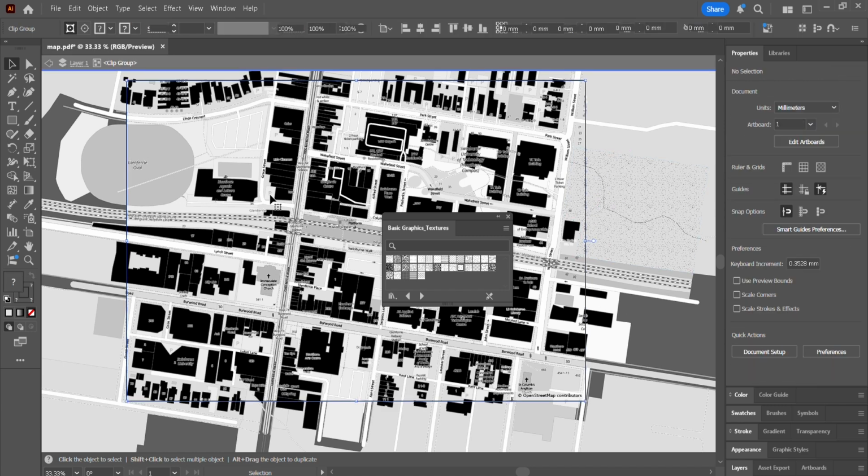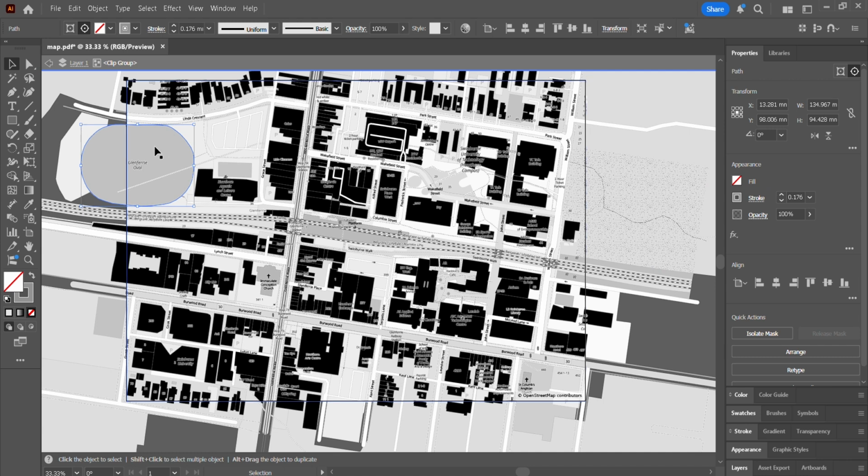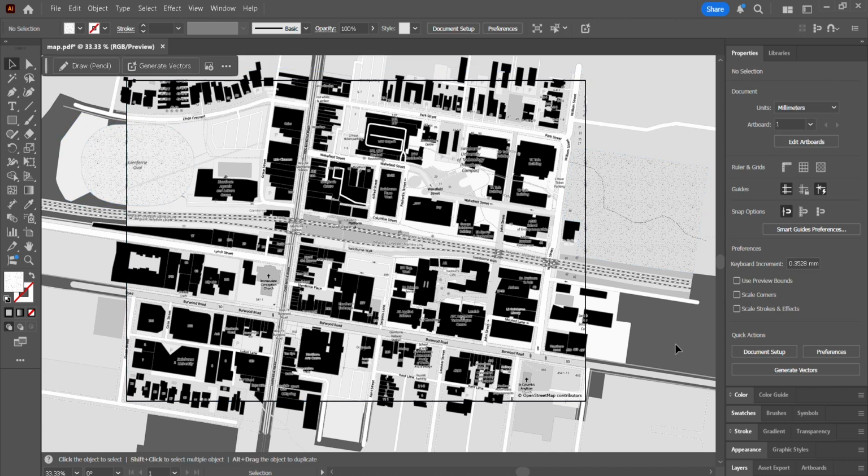And I can do that with Glenferrie Oval. Obviously the oval is going to be grass as well. Because the oval and the grass on this park area here were slightly different colors based on the QGIS import properties, so that I don't need to go through that whole process of selecting the properties again, all I'm going to do is select Glenferrie Oval, click I on my computer keyboard, select the grass texture here, and there we go. That one's the same.